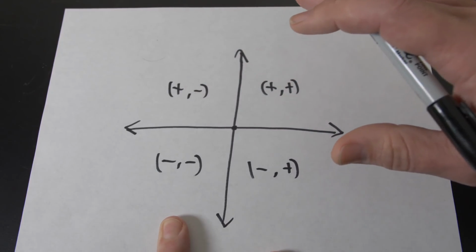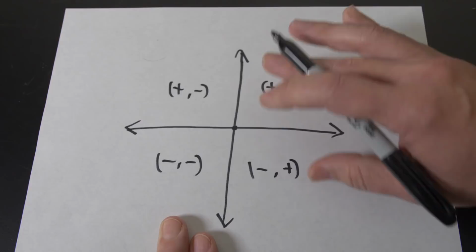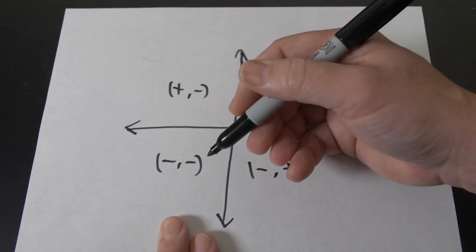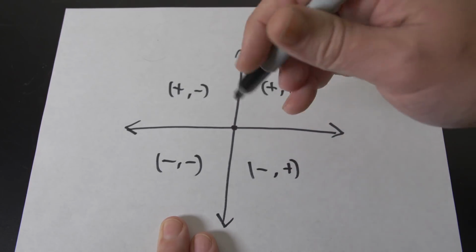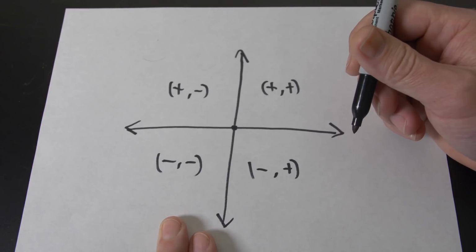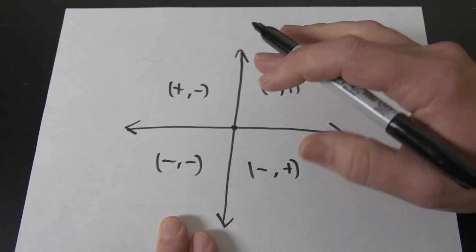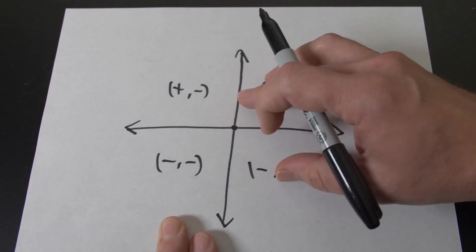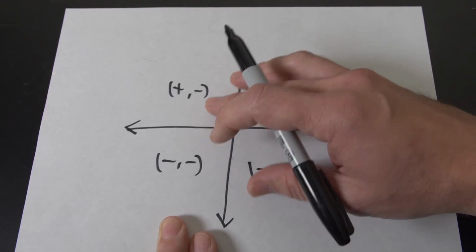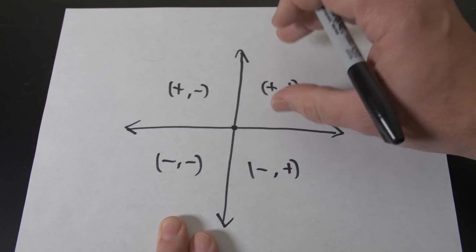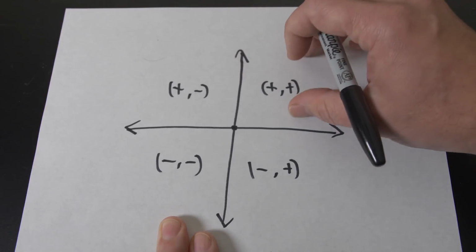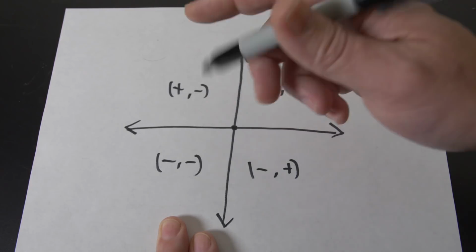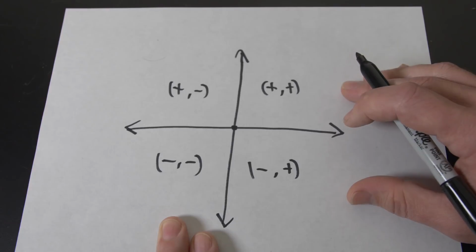Now, some of the DIY programs that we're going to talk about here in a few minutes use the 0, 0 coordinate not as the lower left portion of your stock material, but as the dead center of your workpiece. And I don't like that approach. My brain doesn't like to wrap around that because I'm seeing a whole lot of negative numbers when I'm looking at the digital readout, and it's just hard for me to orient in space. I really like working in the positive quadrant, so that to me is the standard that everybody should be going by. But hey, chime in the comments if you have a good reason why the 0, 0 would ever be the center of your workpiece.